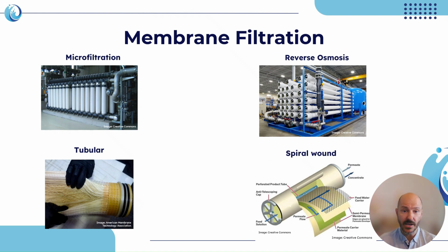streams, and bioreactors. Spiral wound filters consist of flat sheet membranes wrapped around a central permeate collection tube in a spiral pattern. Spacers are placed between layers to create channels for feedwater and permeate flow. They're commonly used in nanofiltration and reverse osmosis systems for relatively clean feedwater. For example, drinking water treatment or tertiary wastewater polishing.